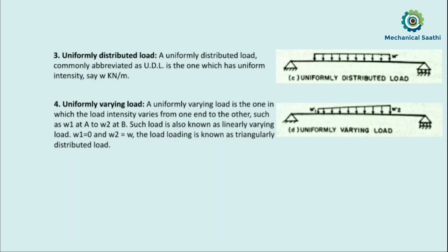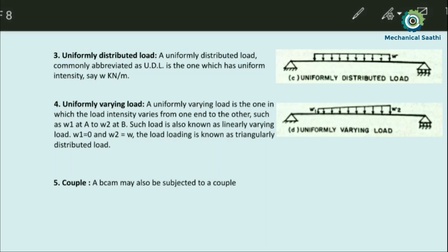Now let us discuss another thing that can also be applied on our beam, which is known as a couple. I think you must have an idea about this. When two forces are applied on a structural member which are opposite in direction with the same magnitude and acting in the same plane, then that system of forces we call a couple.